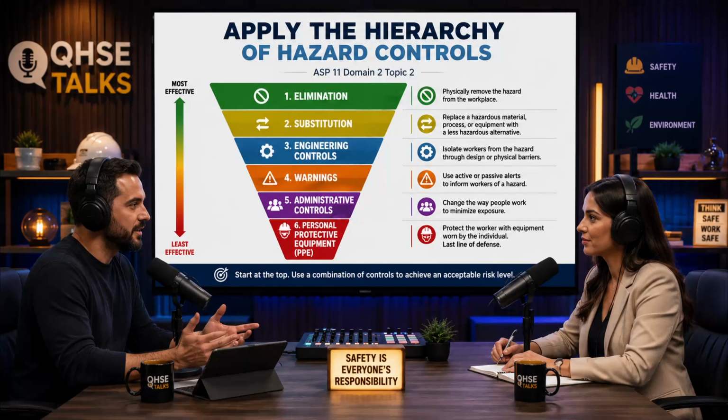They might apply the lock to the wrong breaker entirely. And the hazard, the electrical energy, is still fully present in the main line. The lock didn't engineer the electricity away. The written program just attempted to manage the worker's interaction with the switch. If the human deviates from the procedure, the control fails instantly.